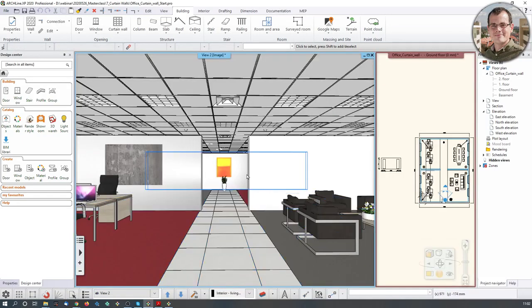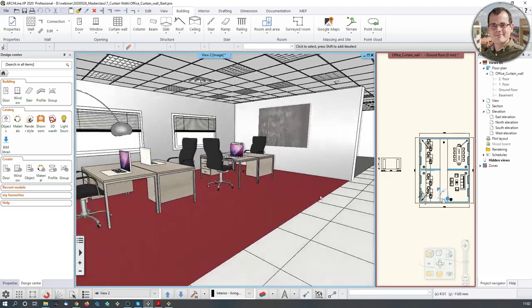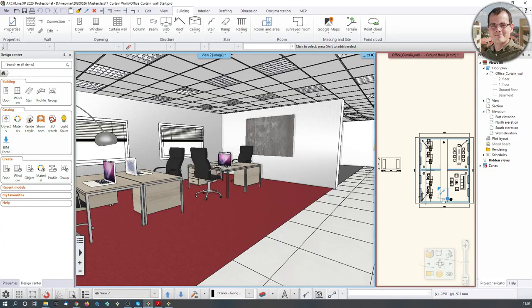This is going to be a very simple office, and I want to create partition walls, which are going to be glass surfaces. So the four things that we are going to look at today are how to create a curtain wall to act as a room divider, and then how to convert an existing wall into a curtain wall, because we can do that too. We are going to look at how to join multiple curtain walls into new constructions, and also how to create unique and customized glass insets. What I'm thinking of maybe is a panel of glass bricks here and there. So we are going to look at all that.